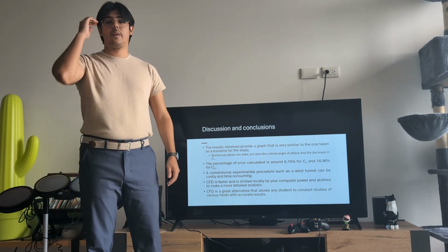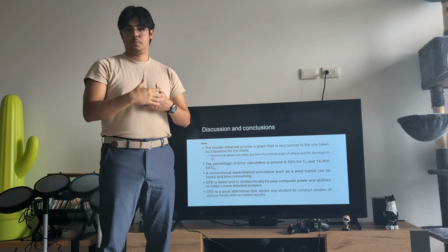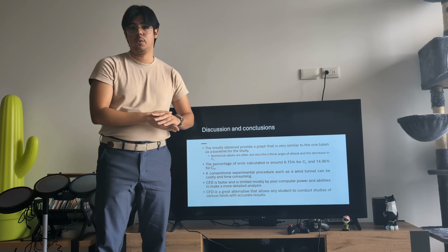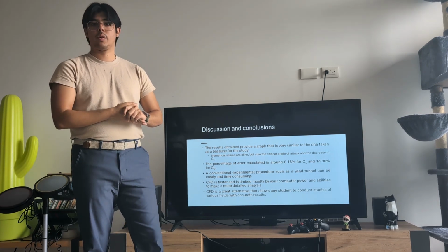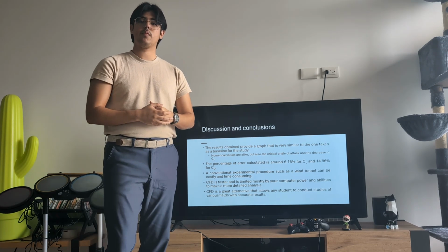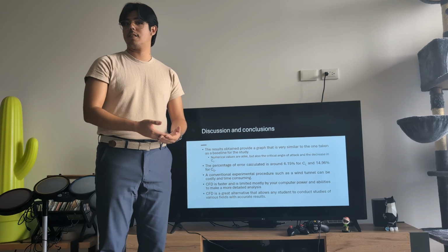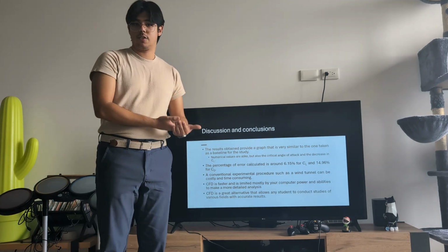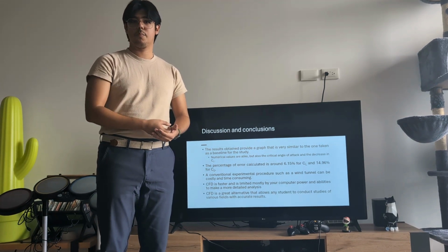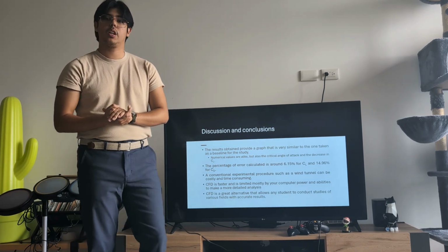Now this is because of the erratic behavior and the difficulty for simulations to actually predict or converge into critical values, but this can very easily be narrowed down, made more accurate by simply making a mesh-independent study, by adding more parameters, by making more boundary conditions, and overall making a more complex situation.